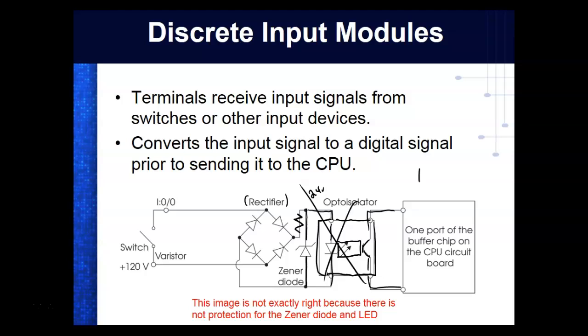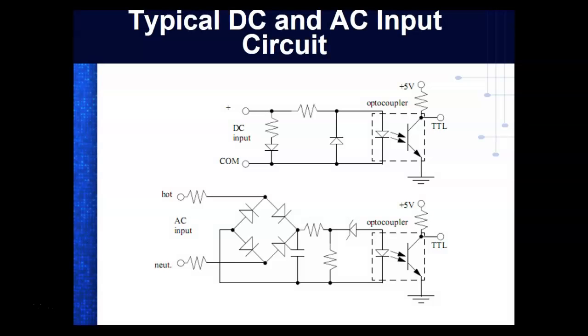And like I said, they're squares. They usually have 4 pins on them, and you can't actually see it. It's inside, but this is just isolation. It isolates the inputs from the internals of the computer, and also it isolates the outputs from the internals of the computer. So this is a typical input port, except for the resistor. This is a typical output port.